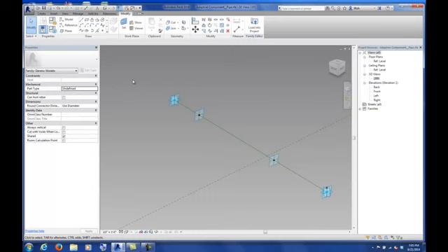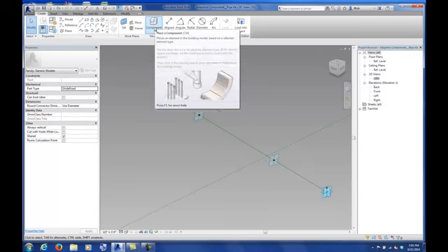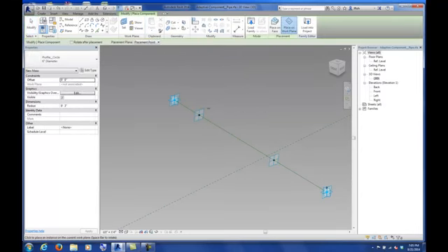Basically what we've done is we loaded a circle into this new file. This circle is considered a component because it's another family that we're bringing into this family. So if you want, you could go to create, and there's this bigger icon called component. And if I pick that, I can now place a circle. So sort of see that? All right.